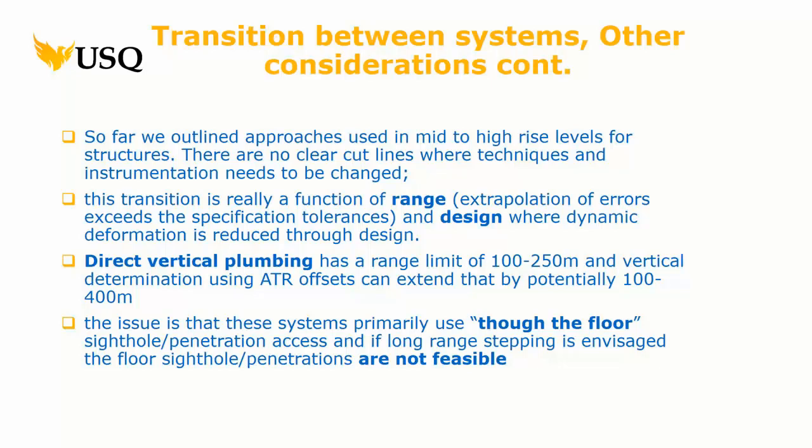But understanding these things allows you to move into other areas. You've just got something put into your head here, going, I can actually integrate GNSS. What would happen if I had a tilted surface, something I can't even set the instrument up on? Can I bolt the instrument to the floor at an angle like this and measure? And you think, well, if I did a transformation between that and the flat, I could transfer those points to what they would be on a flat plane. It's waking your thinking up a bit.